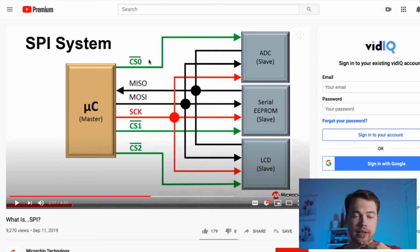So for example, if this chip select is equal to 1, this is equal to 1, and this is equal to 0, then the first two are going to ignore the message, and this one is going to understand that he's being talked to. If you set all of them to 1, then although you send in the data, each one of them is going to think that you're not talking to him, and each one is going to ignore it.